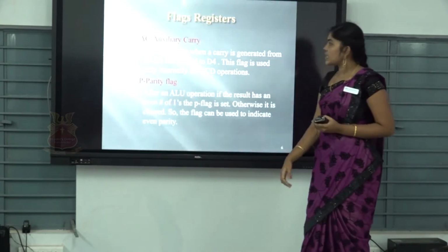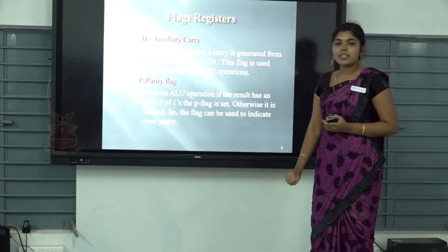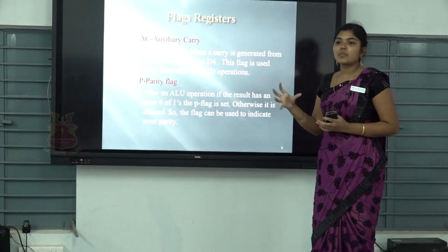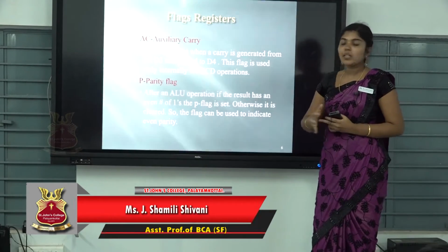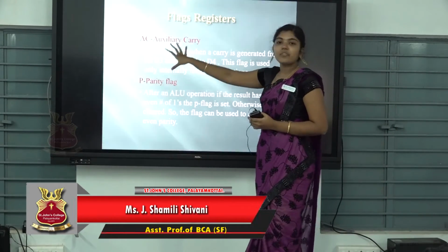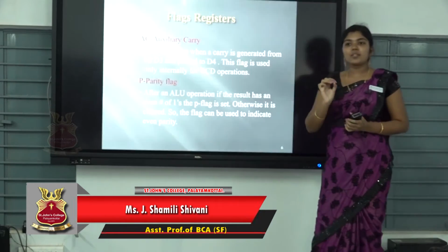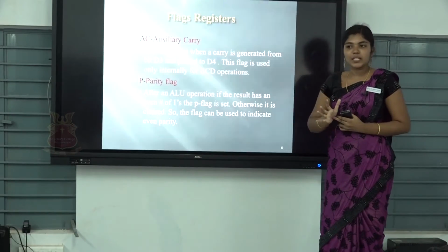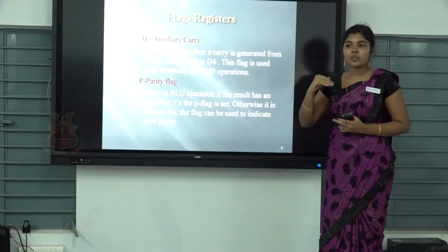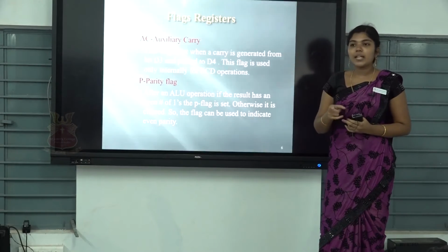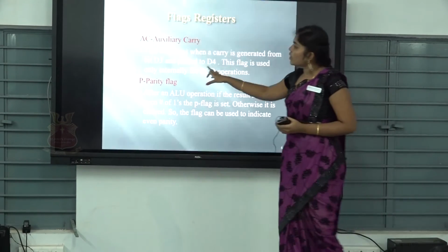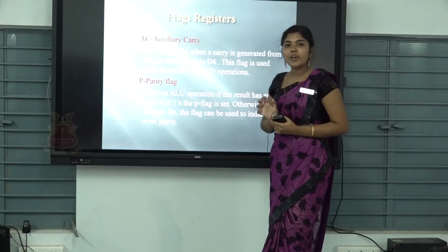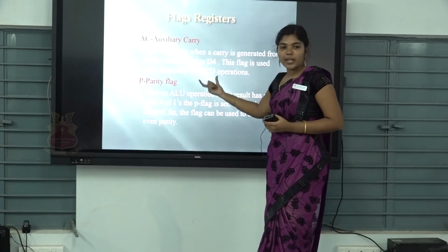Next one is the auxiliary carry flag. The auxiliary carry flag is not accessible by the programmer, so it is only used by the computer. The main function of this auxiliary carry is that it is only used for BCD addition. I already told you about BCD addition; you have studied BCD addition and subtraction in digital design classes. So the auxiliary carry is used only for BCD addition.